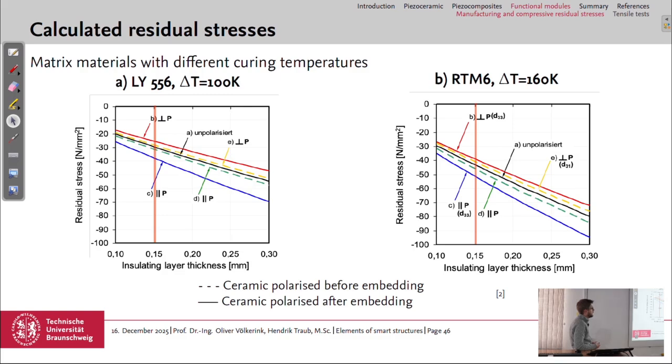You mean if the layer thickness affects the maximum elongation of the transducer? Maybe a bit, since this is the structural material which acts against the actuator, but since the polymer has a stiffness of maybe 3 gigapascals compared to the 40 to 60 of the ceramic, I would say that the effect is not large.